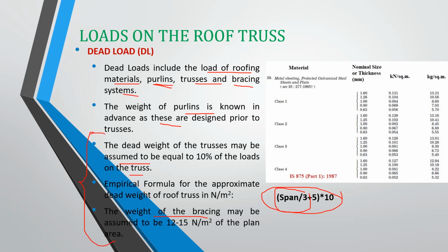We will do the modeling of our truss in our software, and for those components that we have modeled, we do not need to care about the dead load of those modeled elements because the dead load will be calculated by the software itself.